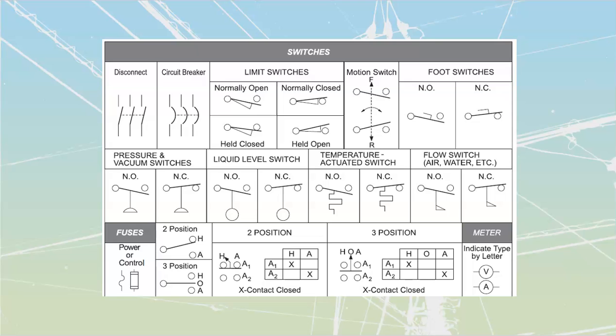But let's start by taking a look at the actual components. Table number 1, which I've broken apart into 2 so that it's large enough for us to take a look at, is going to be a set of symbols that we're going to use inside of schematic diagrams. In wiring diagrams or pictorial diagrams, we're going to be using actual pictures, like those contactors that I've been showing you a couple of times, the overloads and things like that, stuff that is representative of the field look. But this is what we are going to use when we're drawing out our schematics.